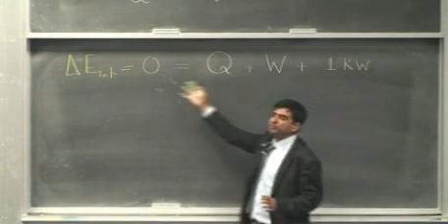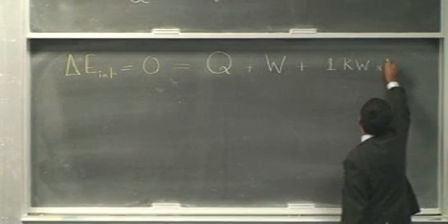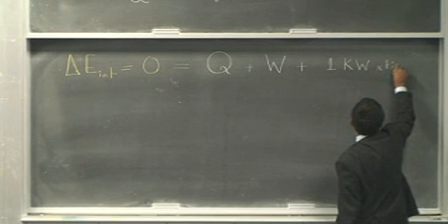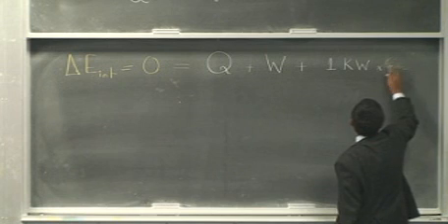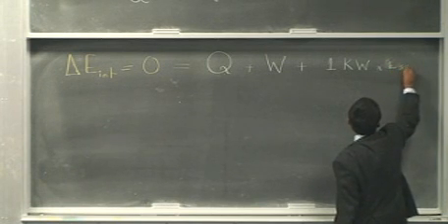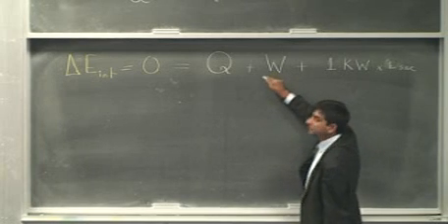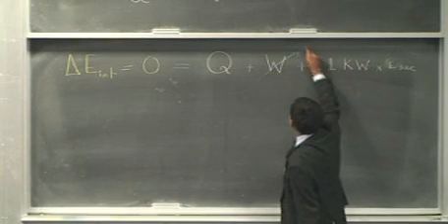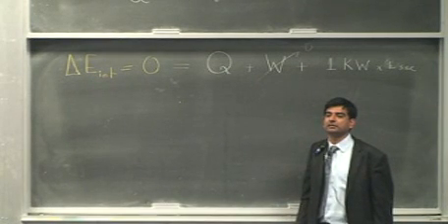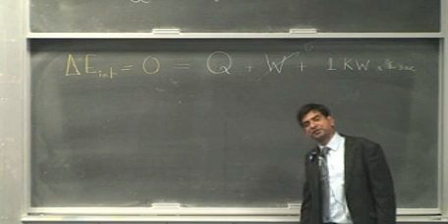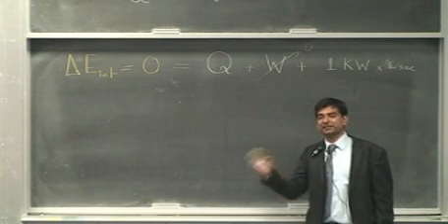And here we have a case of electrical energy input, E electrical, and that is 1 kilowatt. We can also talk about per unit time, so let's multiply this with 1 second. So what is the value of W? 0. Right? Because the temperature remains constant. There is no change in temperature, which means there is no change in the internal energy.